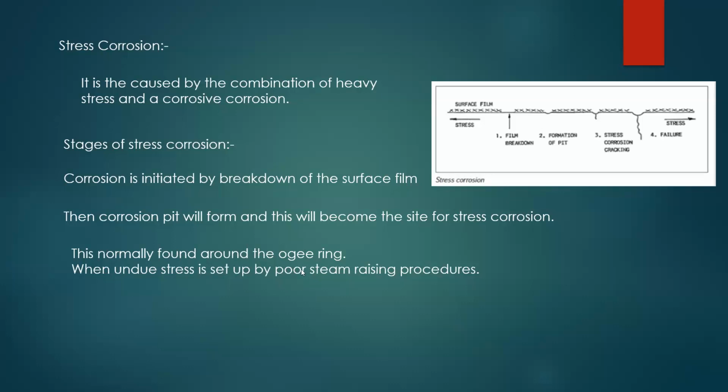Basically, sir, the furnace is attached to the boiler shell. Okay, you are correct, but we will see it in depth when we do the boiler. For the time being, just remember the area. So where was your general corrosion occurring? In the water tube, on the shell, where your water level is changing. This kind of corrosion takes place in the gauging area.